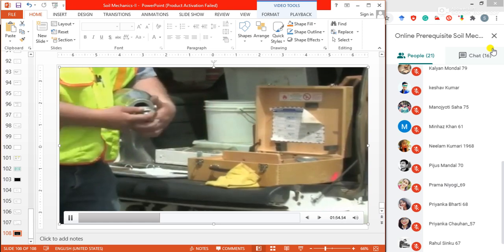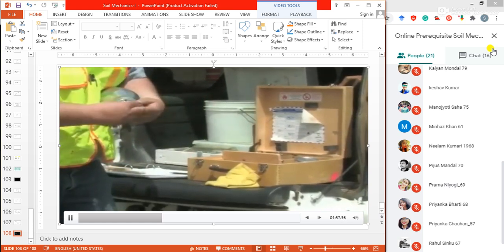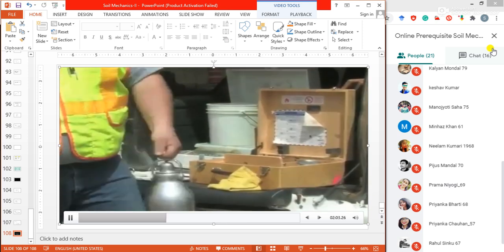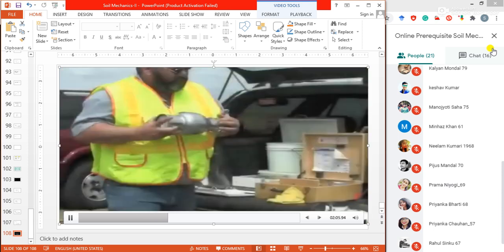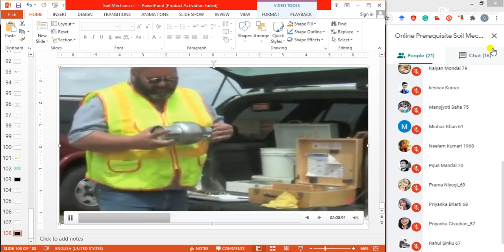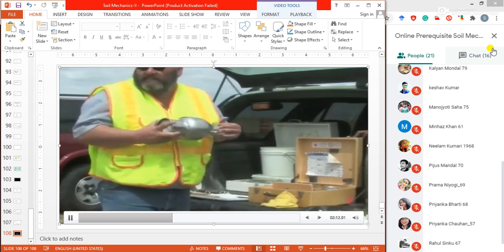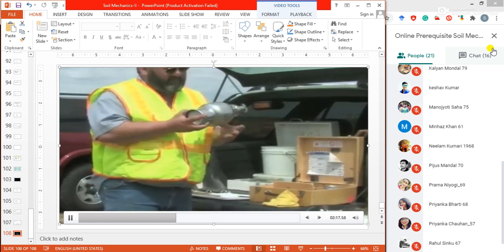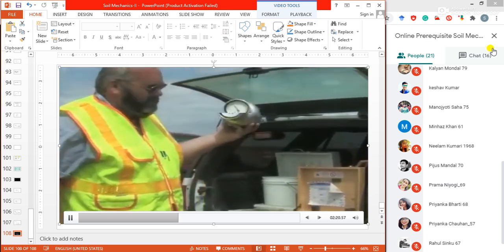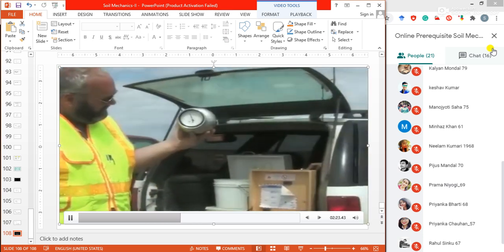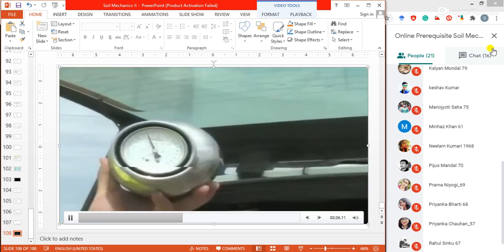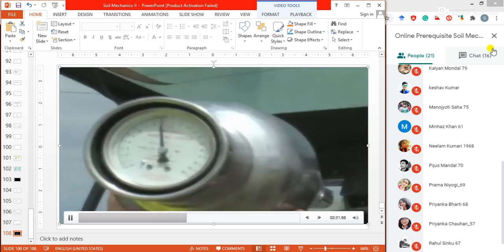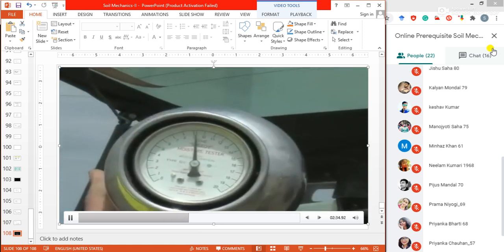Holding the speedy moisture tester in a horizontal position, place the cover on the end. Bring the stirrup in position and tighten the top screw to seal the tester. Shake with a rotating motion to put the sealed balls into orbit around the inside circumference of the tester. Rotate the speedy moisture tester for 10 seconds and rest for 20 seconds. The shaking and resting process allows the reagent to react to the moisture in the soil. This process mixes the soil and reagent together, breaks the soil down and completely dries the soil sample. The moisture reagent mixture creates the pressure that is registered on the gauge indicating the moisture percent.